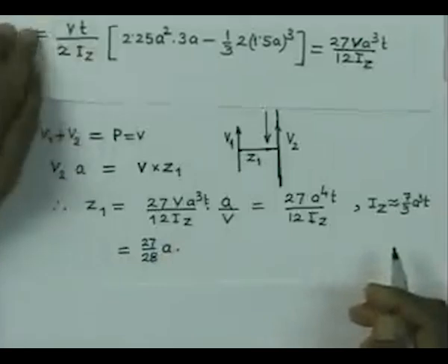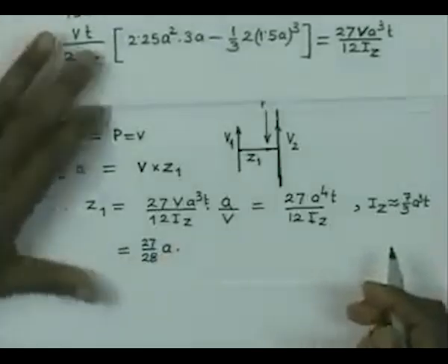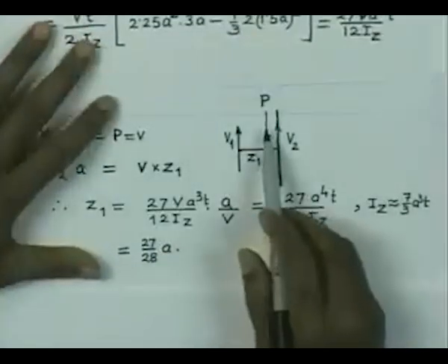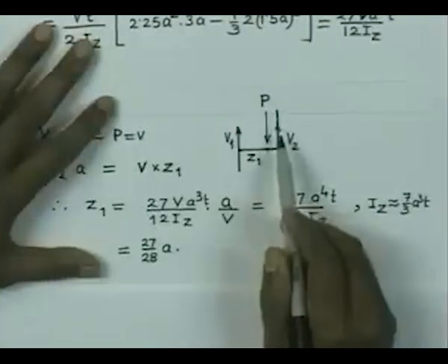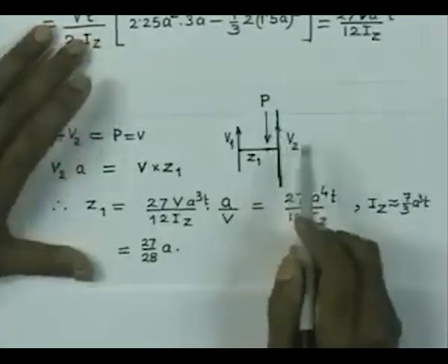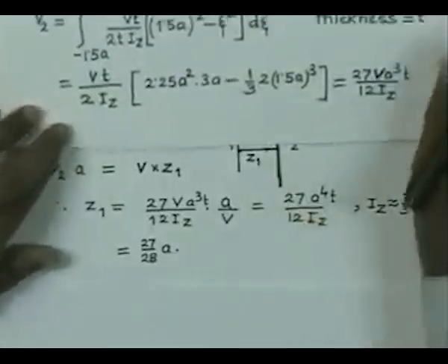So, it means that the plane of the loading must pass through a point which is closer to the longer arm, so that the moment balance will be there. So, we have now got two cases, and we have seen that the location of the shear center needed nothing other than the orientation of the external load, and we have been able to find out the location of the shear center.